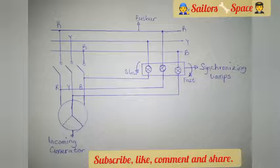If you look at the diagram, you can see that the synchronizing lamps are connected between the three phases of the bus bar and the incoming generator. On the bus bar we have the red, the yellow and the blue phases. Same also on the incoming generator, we have the red, the yellow and the blue phases.